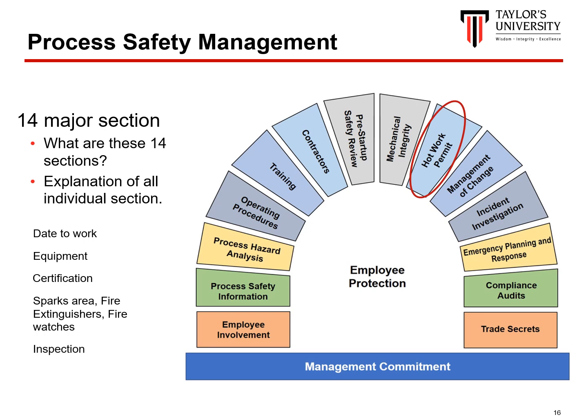the identification of fire watches, and inspections before work, authorization signatures, identification of flammable materials in the area, and of course, verification that the surrounding area is not explosive, verification that the combustible materials are removed or covered appropriately, identification and closure of any open vessels or ducts, and verification that welded walls are not flammable.